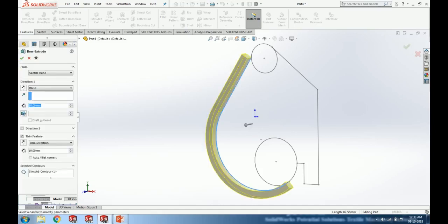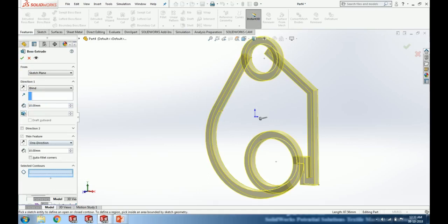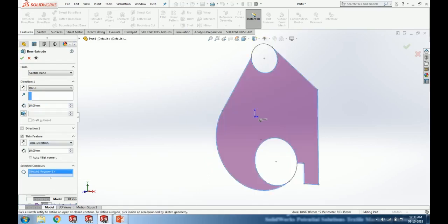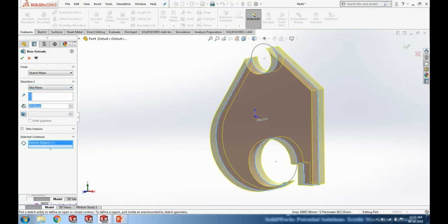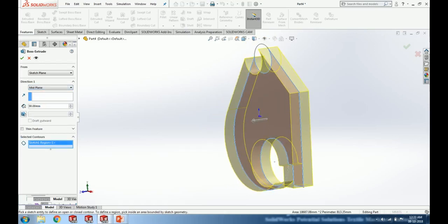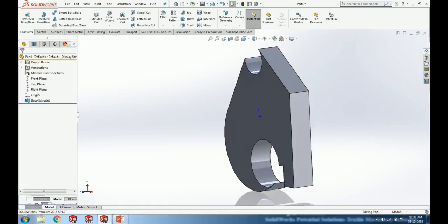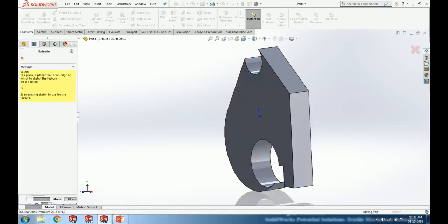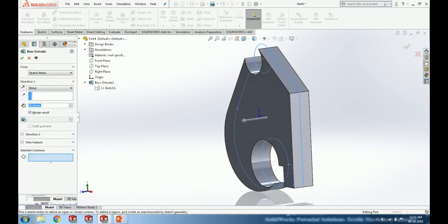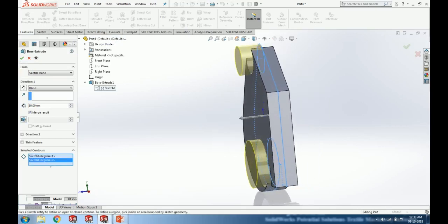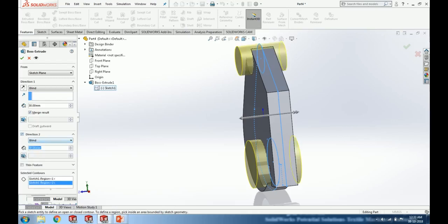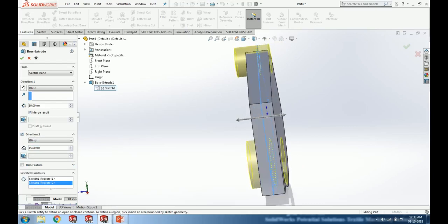Here I want to make a contour of this part with a thickness of, for example, 30 mm, and you can see the model changes uniformly. Next I want to make these extrusion cuts. Here I am using these seamless sketches, and this time the boss extrude. The directions can be easily controlled in different ways. You can see the right-hand side, the end corners throughout the faces.